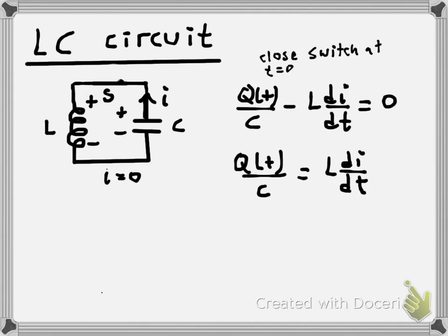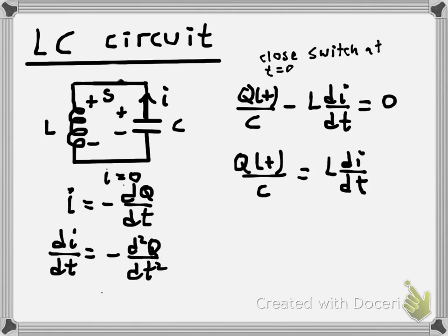That's a differential equation. There's one more step that we have to do to be able to solve it, which is that the current that is flowing out of the capacitor is discharging the capacitor. So we have that dq/dt is negative, and since we assume that the direction of the current is positive as indicated, we must have a negative sign in front of it to indicate that it's a current due to the discharge of the capacitor. So I should be equal to minus dq/dt.